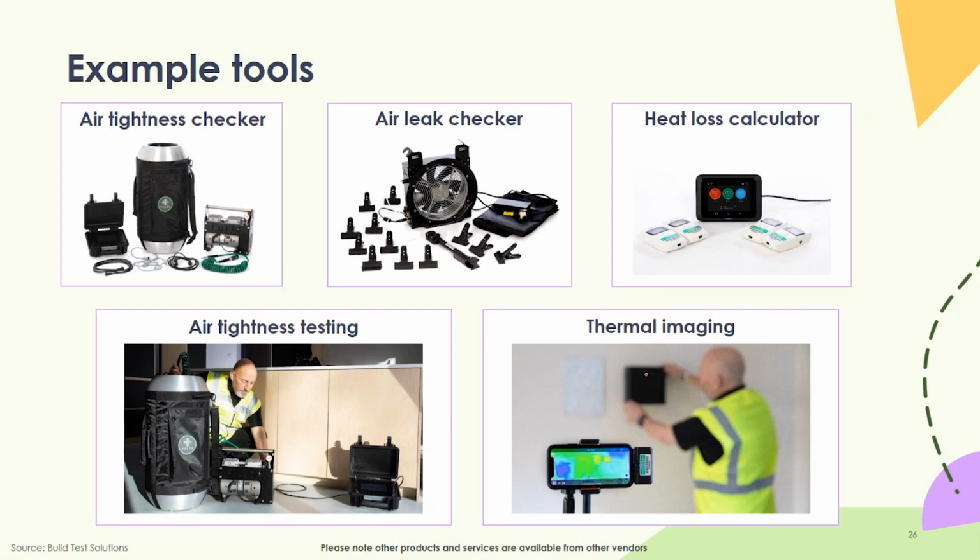And then this one on the bottom right is Heat 3D. So this is our thermography based technique for measuring U values. The alternative there would be heat flux plates. But the innovation around Heat 3D is that this tripod can be set up and a measurement run of the in situ U values within the space of an hour, whereas with heat flux plates, you would typically need to leave those within the property for a minimum of 3 days, typically a week. So again, it's just that little bit more disruptive for an occupant to leave sensors in their home, sellotaped to the wall and things.